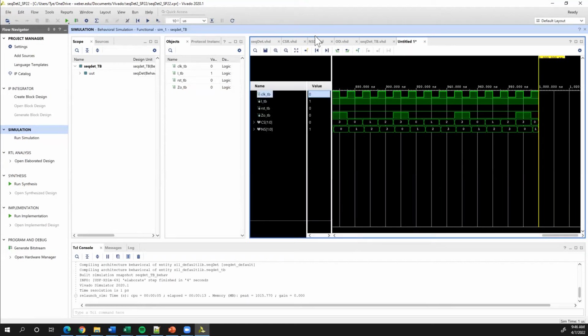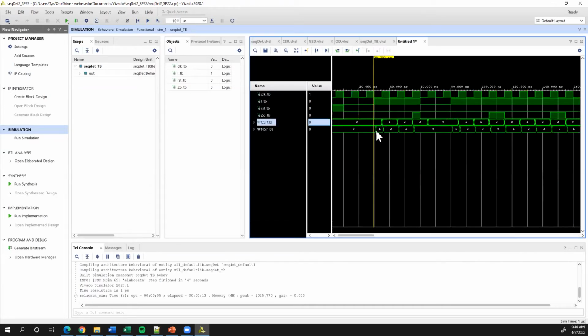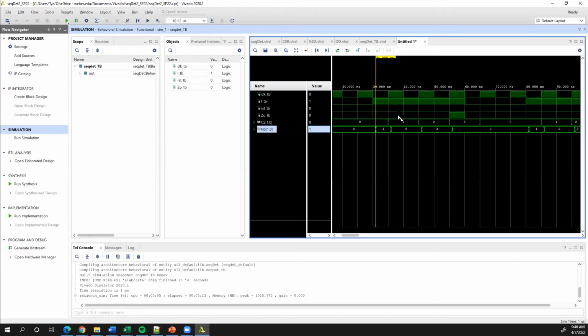now what we can do is if I go look at what's actually happening now, you'll notice that the input changes and then 1 nanosecond later, my next state changes. Because I've now introduced a 1 nanosecond gate delay. And that can help you, especially if you have signals like in project 2 that feed back around on each other. If they all change at the same time, it can be hard to see which one causes the issue, because they may all go dual driven and you may not be sure which one is doing it. Whereas if you introduce these delays, sometimes it's obvious that, oh, this signal is going dual driven first, therefore that's likely the cause of my issue.